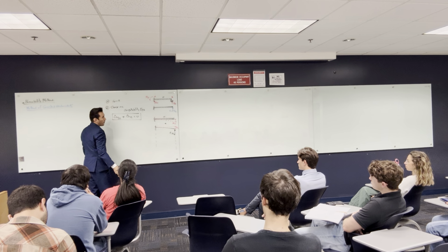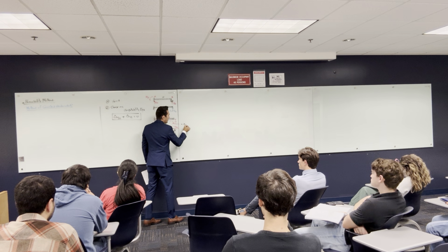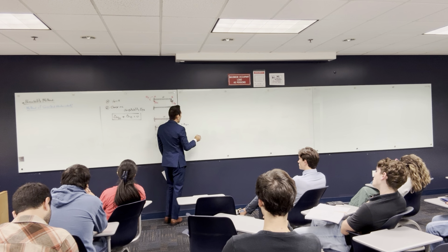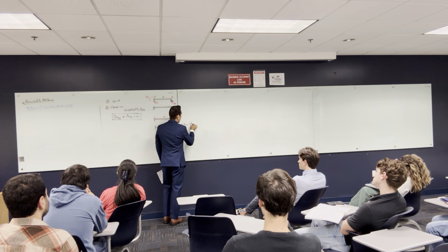All right, so the thing is, we find a way that is much easier to get the value of the delta 1. By the way, if you guys remember from the virtual work, and I believe you got it in the exam, delta 1 for this system, the cantilever, was equal to, I believe, WL to the power 4 over 8EI. Something like this. It has a general equation. And if you have a concentrated load, if you remember, delta 1 for this system with concentrated load is PL cubed over 3EI.